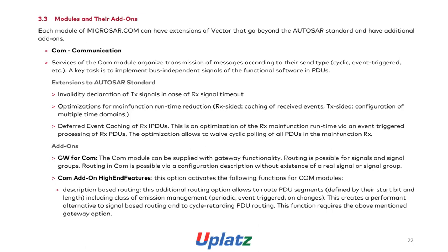RX-sided caching of received events, TX-sided configuration of multiple timing domains, deferred event caching of RX I-PDUs. This is an optimization of RX function runtime and event-driven processing of RX PDUs. The optimization allows cyclic polling of all PDUs in main function RX add-ons.